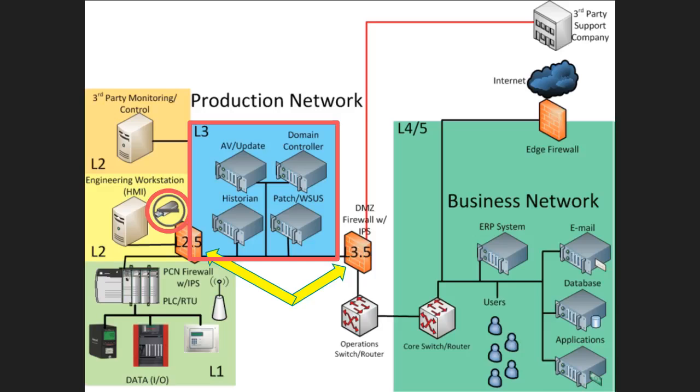Now we're going to look at my model again, and if you notice here, we've added some security. We've added IPSs to our DMZ firewalls here. We have actually created a whole new, we've expanded the little L3 here for the production network. We have AV update, we have domain controllers, we have a patch WSUS system. So we actually have created an infrastructure specifically designed for patching and managing ICS environments.